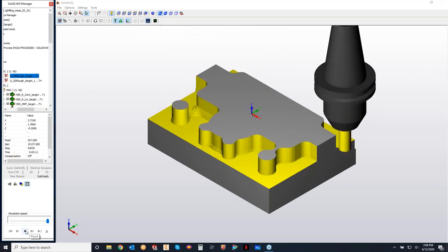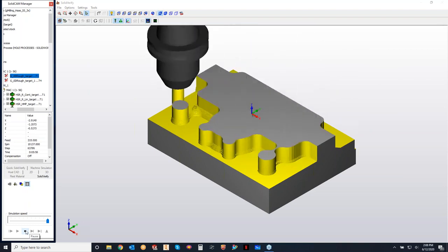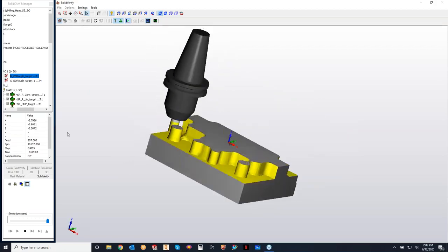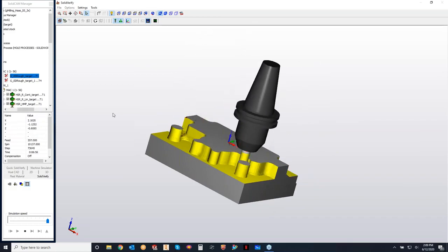Yeah, and this is really nice too, because I'm just kind of remembering back when I was at my old shop running this. You forget maybe to turn on the coolant option, or maybe as it comes through, instead of using flood coolant, maybe I wanted to use through tool coolant on this different drill bit and stuff like that. So definitely a real nice tool, and with the price of everything, it's extremely affordable.